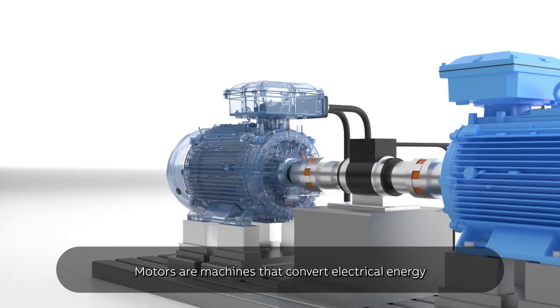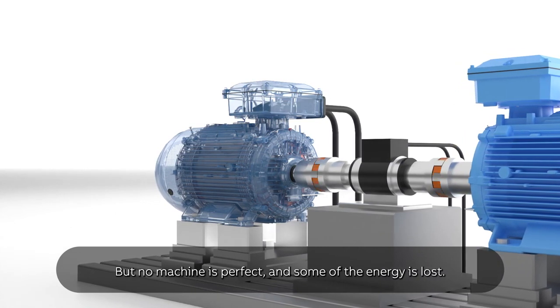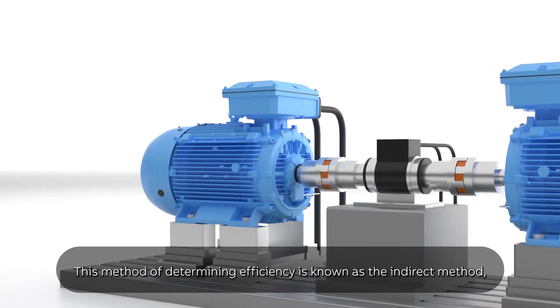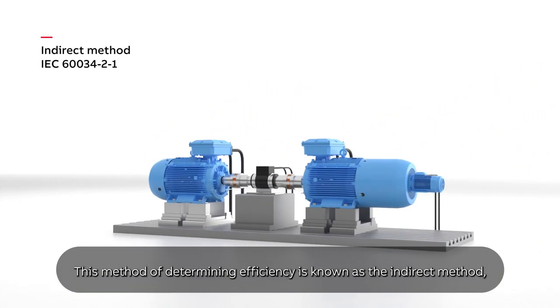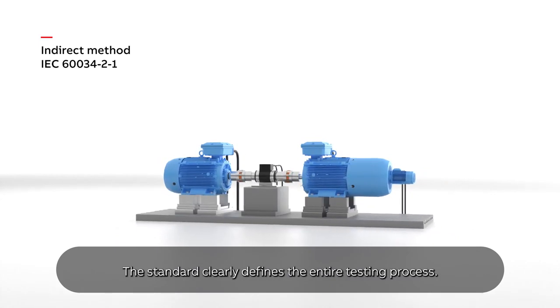Motors are machines that convert electrical energy into mechanical energy, but no machine is perfect, and some of the energy is lost. By measuring these energy losses, we can calculate the motor's efficiency. This method of determining efficiency is known as the indirect method, and it's specified in an IEC test standard. The standard clearly defines the entire testing process.